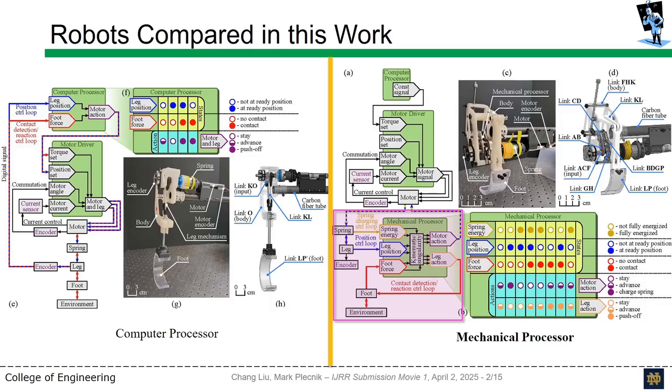A kinematic singularity mediates these mechanical signals, dictating actions of the motor and leg based on a combination of component states. Unlike digital signals, some of these mechanical signals take on relatively large magnitudes and can be directly used to perform useful work themselves. For example, a kinematic singularity inhibiting motion leads to torque buildup in the series elastic element, indicating the position set point has been reached.